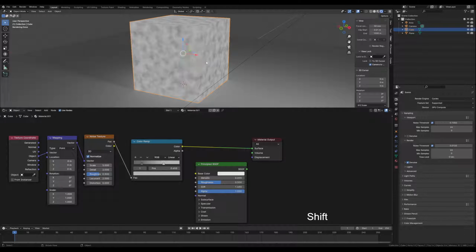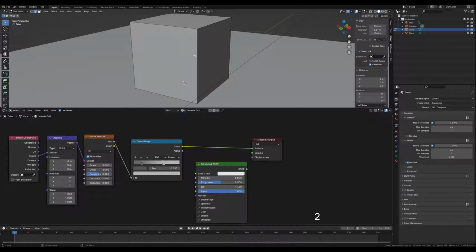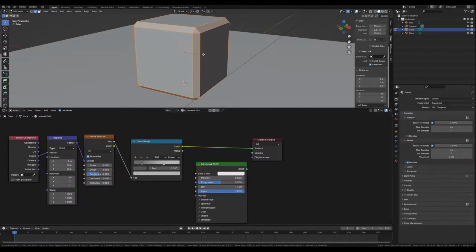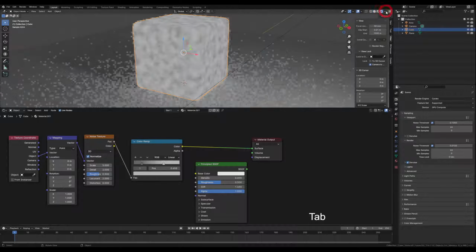Okay. One more thing I forgot. Let's add some bevel to this cube. Okay, Shift Tab to edit mode. Let's change to shading viewport. Okay, and press 2 for edges. Select all and Control B to bevel. Let's make it that way. Maybe this much. Scroll to multiply this bevel. Okay, maybe this much is okay. Let's change it to render view.